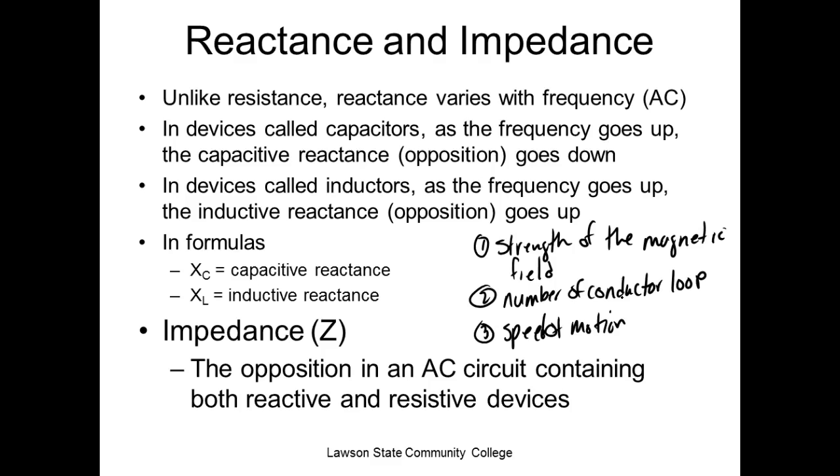So if your car has an alternator, you don't change that, right? Now the problem we have with automobiles is they're constantly changing what? The speed, yeah. But what we can do is we can change the what? Strength of the field. And that's the way your car regulates. So what happens is if the output of your alternator tries to go up when you step on the gas, your regulator decreases the strength of the magnetic field, which causes the voltage to maintain. And that's what the regulator on your car does.